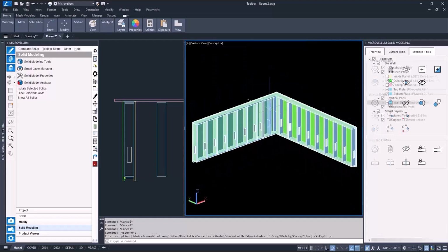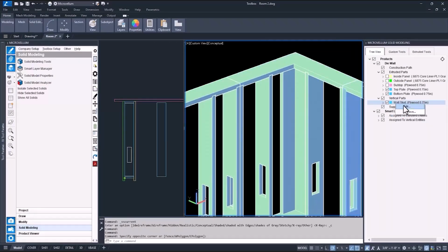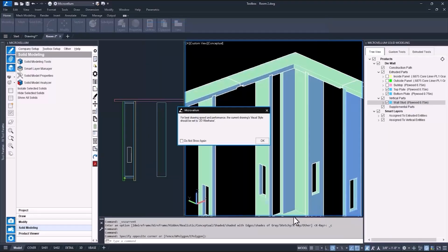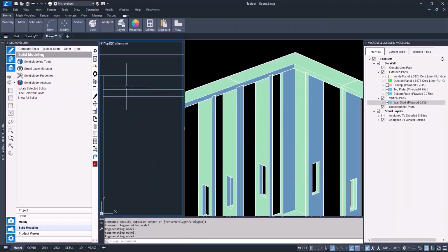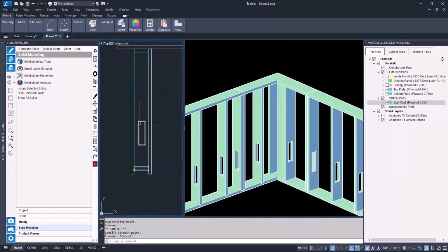Next up are the dowels. First changing the setting in the smart layer for use dowels to true, and then resize the part so it fits between the top and bottom plates. After that's done, the 2D objects that represent the dowel holes need to be drawn.